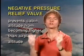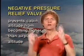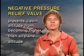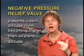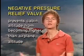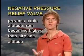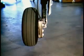It prevents having pressure press inward on the aircraft as opposed to having it press outward the way that a pressurized aircraft is designed to do it. So it prevents the cabin altitude from becoming higher than the airplane altitude, and the way it does that is simply lets ambient outside air in if the cabin altitude is getting higher than the actual airplane altitude is.